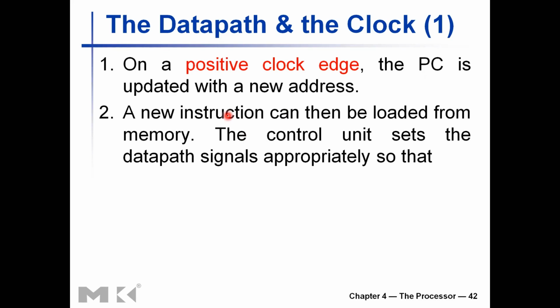So instead of the old instruction encoding, the control unit will have the new instruction encoding just a little bit after the positive clock edge.